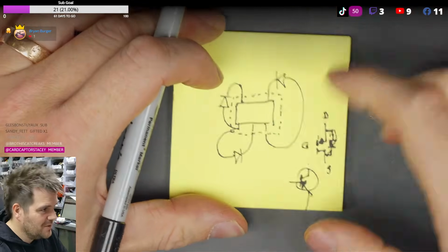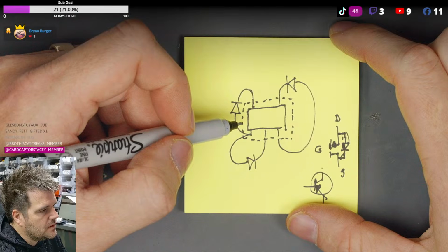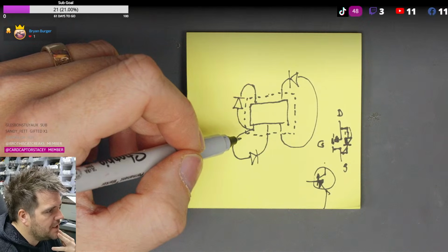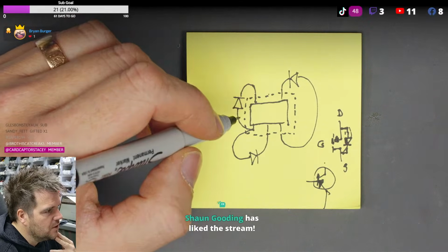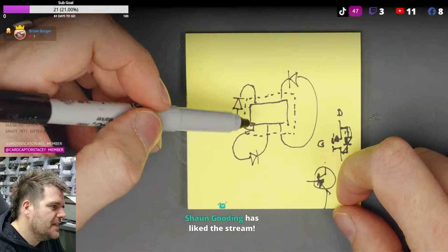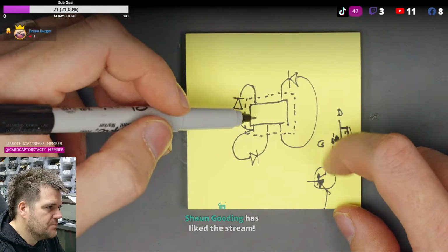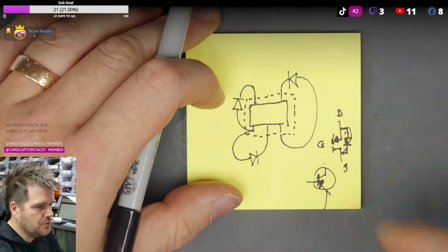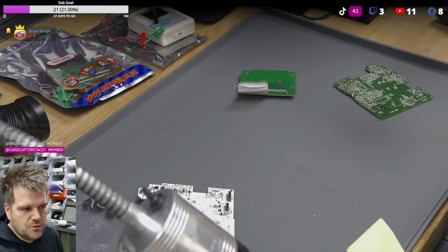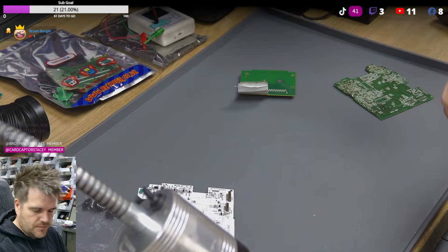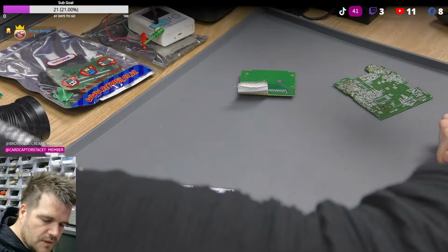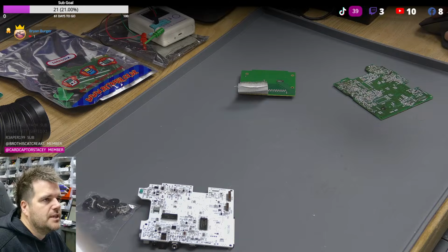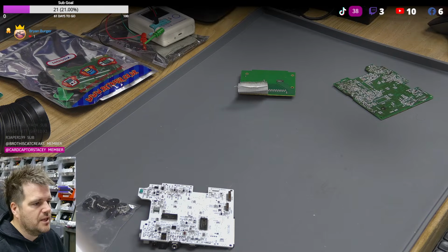So I think the best thing to do is, I don't know whether we look for transistor packages that are 5-pin and just give us some ideas, or put it in the tester, because nothing's standing out to me as obvious here with just these diodes in these positions, what orientation or package this might be. And the other one was quite hard to figure out because it was an epitaxial, which is not that common. So I think it's going to be a DigiKey search for the minute. Let's see if we can find anything that maybe helps us.